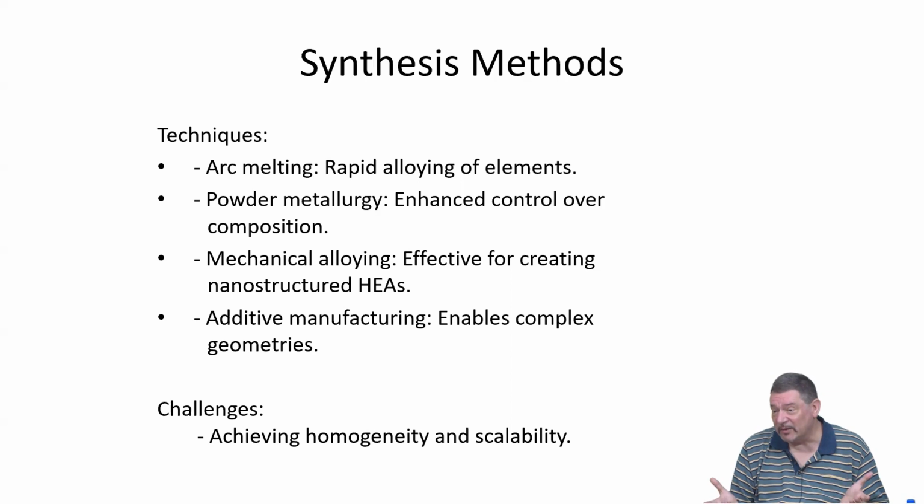They are highly unstable, obviously, so if one wants to compact them and make a bulk material out of it, then you have to anneal, probably under specific conditions, spark plasma sintering, or maybe applying at least some pressure and temperature in order to make bulk shapes.